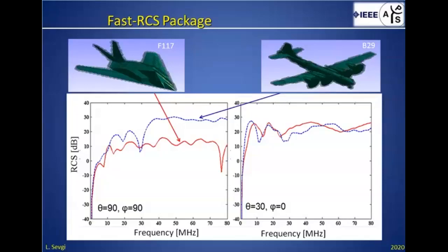So although the left one is low visible target, depending on the radar direction, the angle of illumination, you can still catch or capture or observe, detect these targets with your radar systems. So the angle of illumination, the angle of the radar, is critical in RCS measurements or radar systems. Next slide, please.